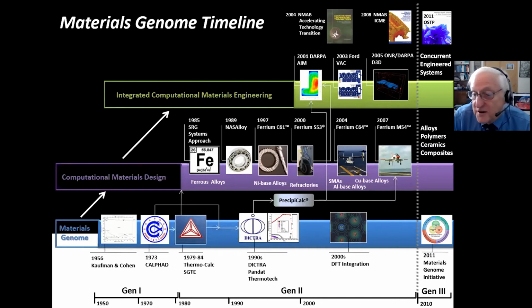And doing that the old way was 90% of the time and cost of getting a material usable. So the DARPA AIM was the first example of doing that, demonstrating it with the case of an aeroturbine disc nickel alloy, but we went on to apply this to steel applications since. So at this point, we've really got over 6 decades of building out the fundamental genomic database structure, more than 30 years of well-established design practice, and now really 20 years of a fully integrated process.